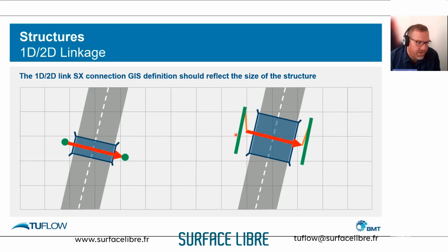So we've got linear coupling, selecting 2 cells that allow us to get the required flow into the culvert and also out of the culvert at the downstream end. So in this case, it's just 2 points at the upstream of the structure. In this instance, we've got an SX line. We use a CN line to connect that to the culvert, and then we've got a CN line connecting back into an SX line. So these are the cells that are connected between the 1D and 2D domains.